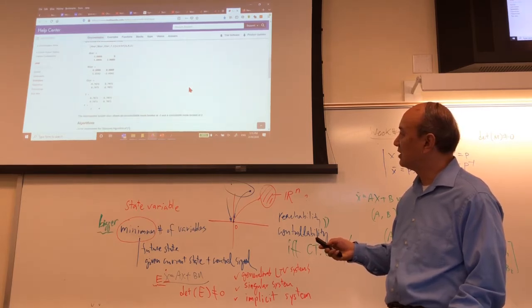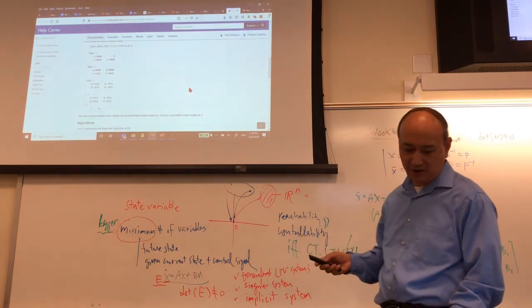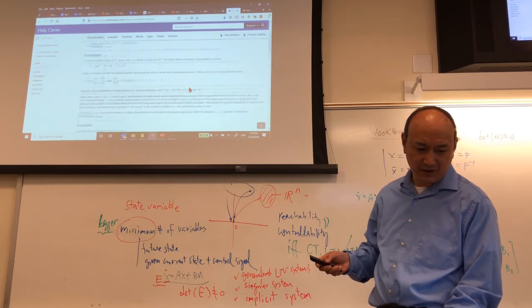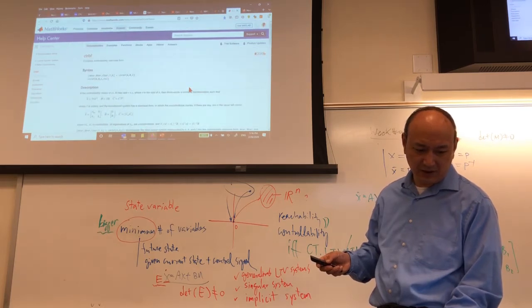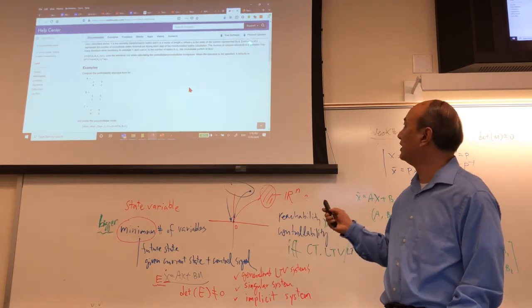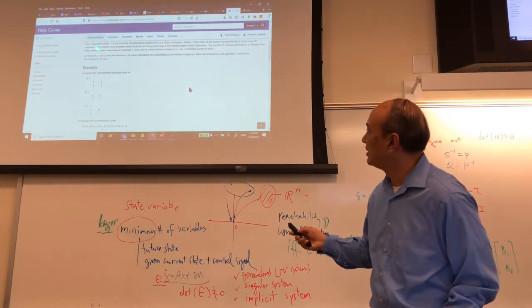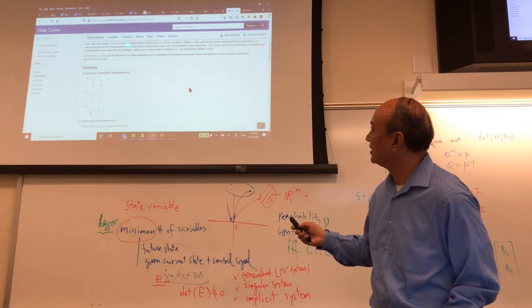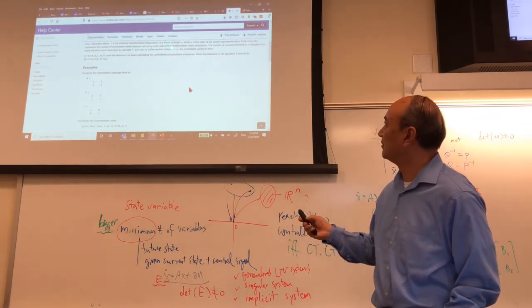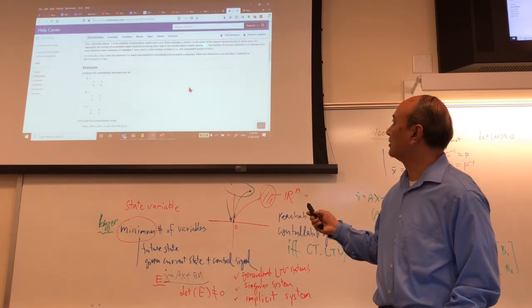T-bar, I think the K will be kind of an indicator. Let me see. The K will give you an idea about which variable is not controllable. Each entry of K represents the number of controllable states factored out during each step of the transformation matrix calculation.